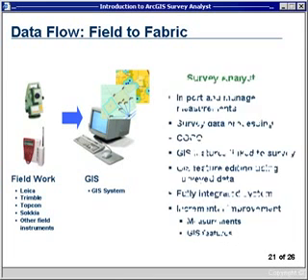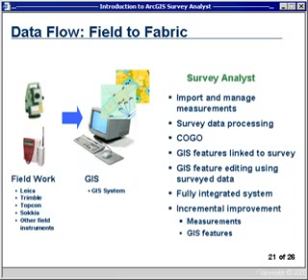So with Survey Analyst, the process looks like this. I'm going from the field work, digital data from the collectors, loading it into GIS, right into Survey Analyst. Now within Survey Analyst, I import and manage that data. So I import it and store it in projects as units of work that I'm used to working with. Within Survey Analyst, I perform the survey data processing that was a separate package before. Within Survey Analyst, I can actually resolve those measurements into locations.